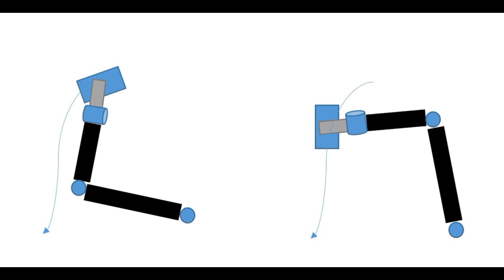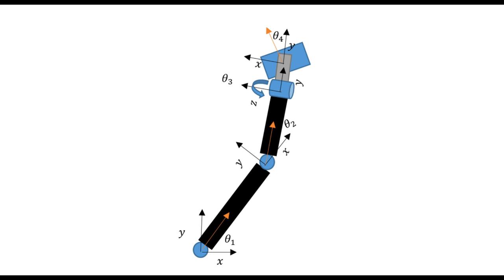The case of θ3 and θ4 is special. θ3 is uniquely used for end effector height control, which allows us to pick and place dominoes. Theta 4, on the other hand, relates to the orientation of the dominoes by the formula phi equals theta 1 plus theta 2 plus theta 4, where phi is the overall orientation in the workspace of the end effector.